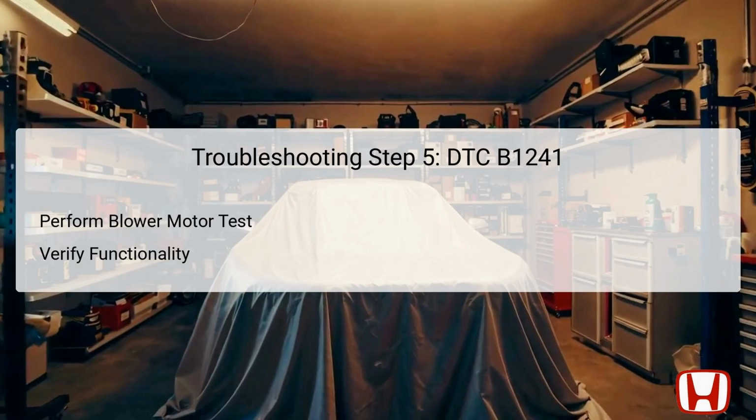If the blower motor is functioning correctly, it should run steadily. If it fails to operate while grounded this way, it indicates an internal failure in the blower motor itself, which may necessitate a replacement. Ensure thorough documentation of results for both functional assessments and any subsequent part replacements.